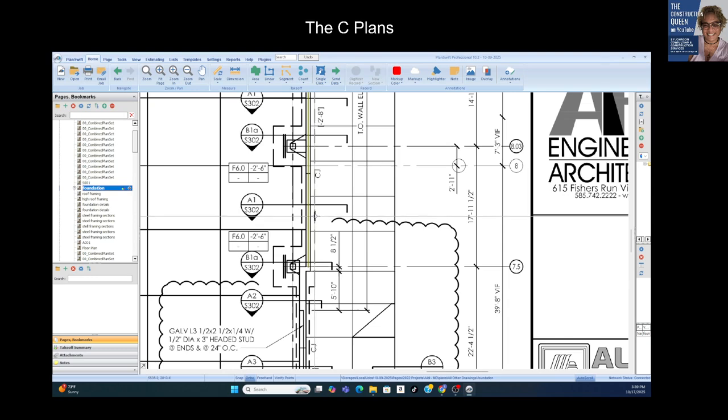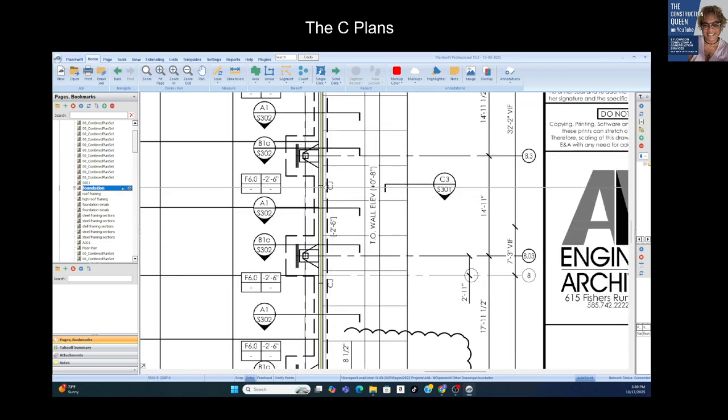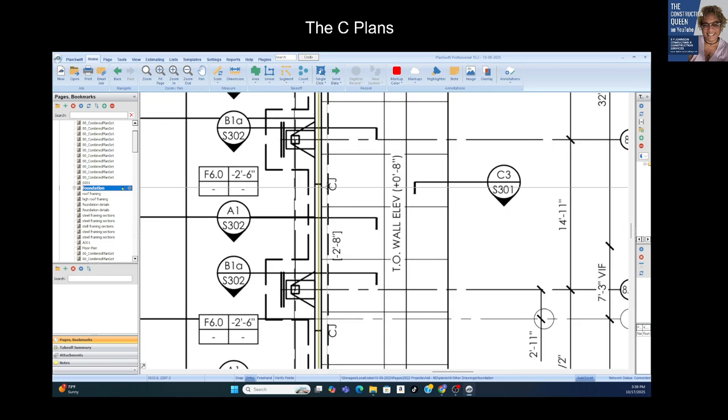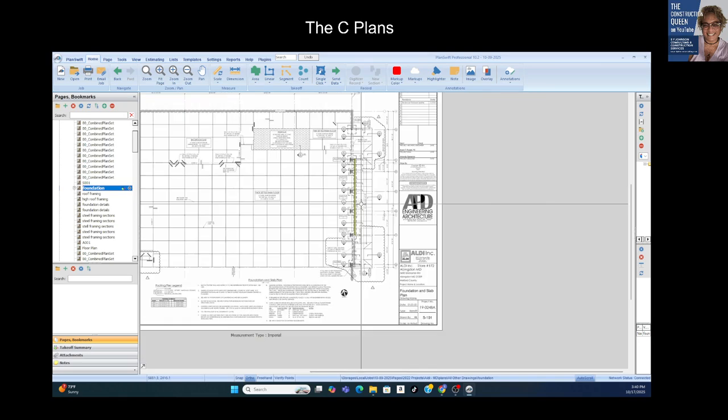And what you're going to see is just the interior construction. So why do you need to see that? Well, if I'm the concrete person, I know that that continuous footer has a depth, a width, and a height, and all of that. And I have to be able to determine what that is in order to do a proper takeoff, in order to determine how many cubic yards of concrete I need, how many linear feet of any particular size of rebar. Okay. And that's what we have to do.